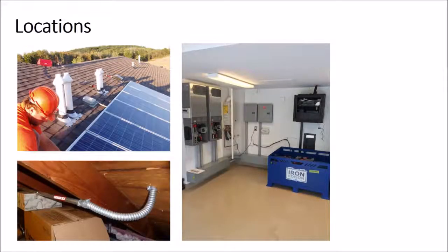So think about your locations. You might worry about temperature sizing. Do I use a 75C cable or a 90C cable? Well, if you're up on the rooftop, that's a very hot environment. That's what the high temperature cable, the 90C cable, is designed for. So yes, you should use a higher temperature rated cable on a rooftop.